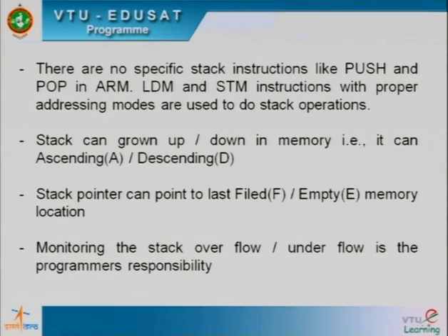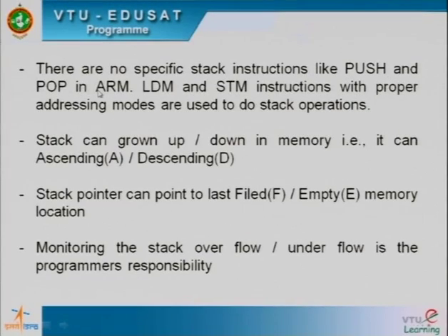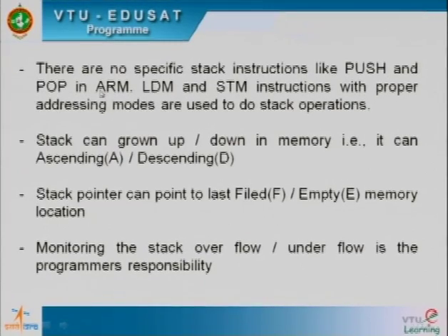What does ARM provide for the stack instructions? There are no specific stack instructions like push and pop in ARM. The ARM instruction set does not provide specific instructions like push and pop the way other processors do. What it provides instead are LDM and STM instructions with the proper addressing modes. We'll see what we mean by proper addressing modes in the next slide.